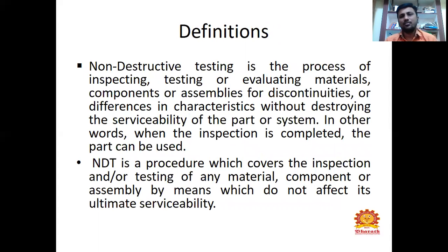Then the definition. Generally, non-destructive testing is the process of inspecting, testing, or evaluating materials, components, or assemblies for discontinuities, or differences in characteristics, without destroying the serviceability of the part or system.